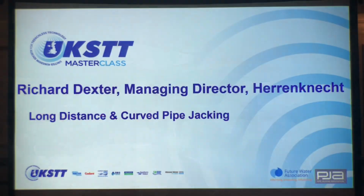Just another one, we were talking earlier about the ground coming on, and somebody mentioned that even strong ground and strong materials move. If you go down the very deep South African gold mines, 3 kilometres deep, the core site, which is 300 megapascals, so 10 times stronger than any concrete you generally deal with, will move a foot in 10 years. It's plastic at that depth. You'd be staggered what it is.